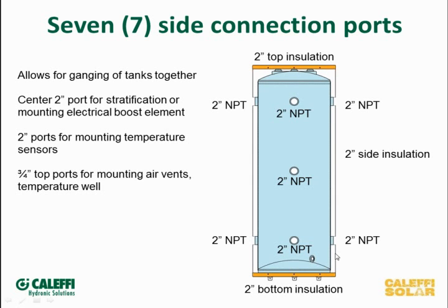So it's foam insulated all around, so you don't have to worry about it sweating and dripping on your floor there. So we'll give you some ports at the top that you can put sensors in. We give you the center port here because that's an ideal place to put the sensor that would operate your heat pump. If you're reading the temperature at the center of this tank, that's the control that would turn the heat pump on. So the heat pump is really looking at this as its load now, not as the distribution side, the radiators or the panel radiators or the radiant tubing. It's looking at this as its load, so that controlling thermostat would go into a port in this tank, and that's what turns it on. The tank gets up to either in the heating season the hot temperature, cooling season to the cooled water temperature, then it shuts off the system, and then you just basically sip off the load on this side of it as needed.